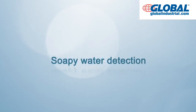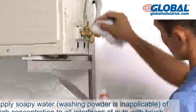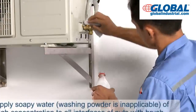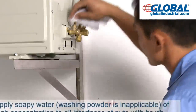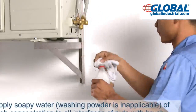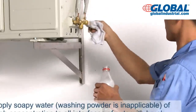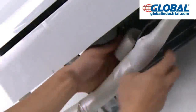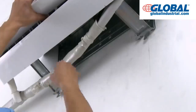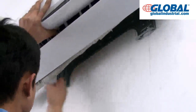Soapy water detection. Apply soapy water of high concentration to all interfaces of nuts with brush. Washing powder is inapplicable. Then observe it for 2 to 3 minutes. Repeat this as needed. If bubbles emerge, leakage exists in the system. Nut should be tightened further. This method of leak detection is equally applicable for indoor unit. After it is confirmed that there is no leakage, insulation sleeve is used to wrap joints.